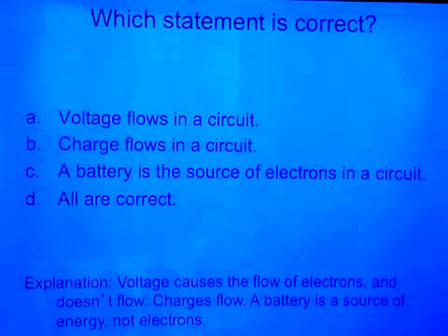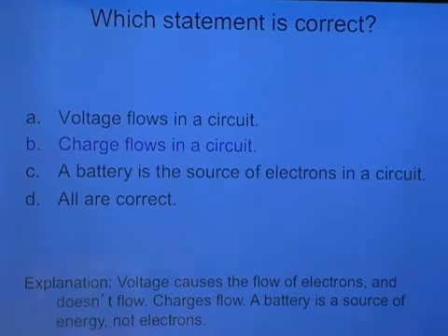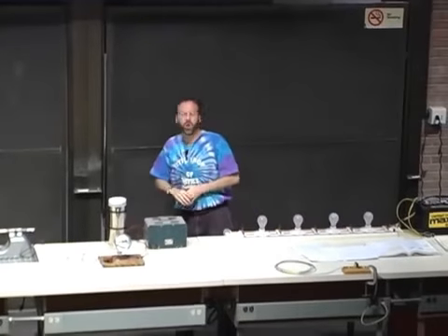Voltage does what in a circuit? What do you think of when you think of voltage in a circuit? It pushes the charge through, yeah. Charge won't flow unless there's a difference in voltage, a difference in potential. If this is at 9 volts and this is at 9 volts, nothing's going to flow between. But if you have this at 200 volts and this at 100 volts, now there's an electric field. The charges feel it and they get moved along.